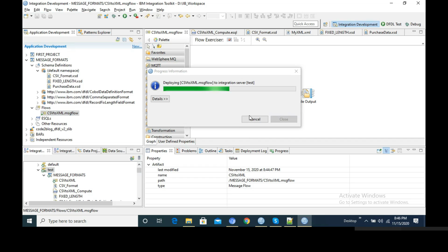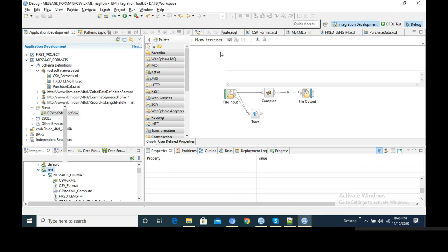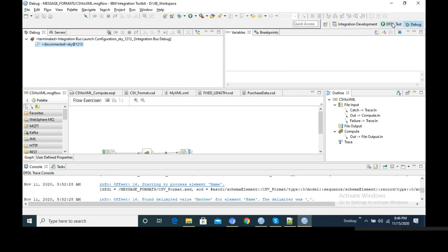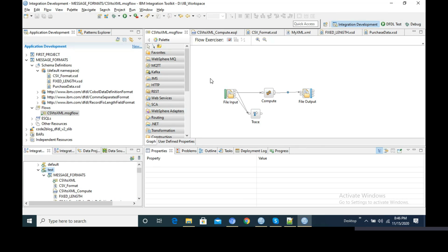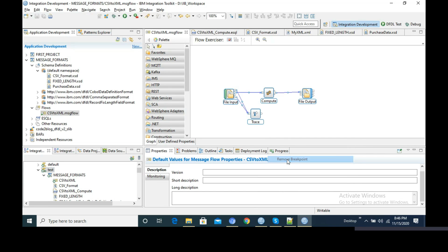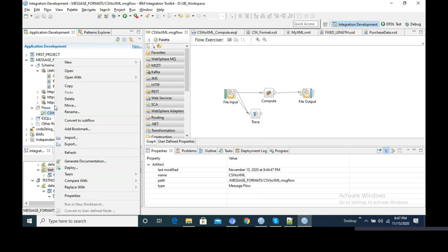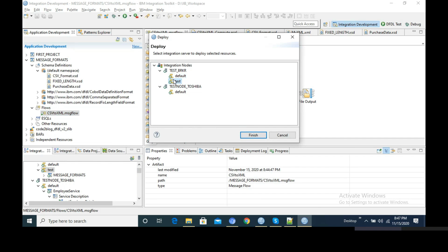It is taking too much time. I think you have enabled debug mode and the flow has not completed, has not terminated. So cancel this and switch off the debug. Okay. Another thing: why do I see a green arrow mark in the test execution group? Right click over there. Oh, here, right? Just say refresh and the arrow mark will go away. Oh yeah, it's gone. It was in debug earlier, and now it has refreshed and the debug breakpoint and everything has gone away.